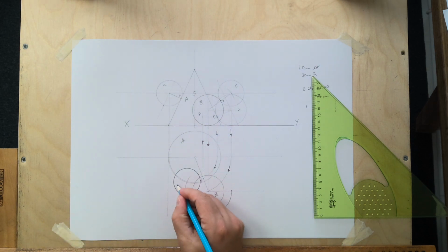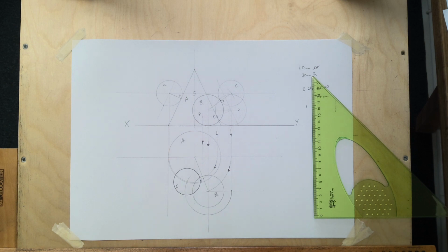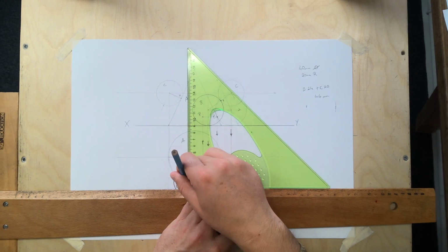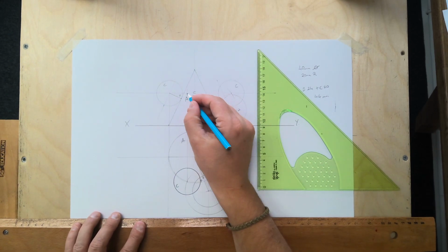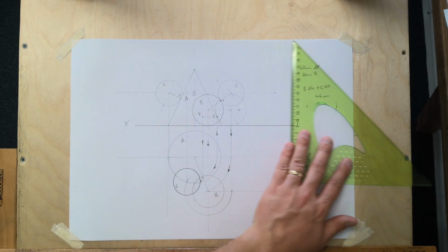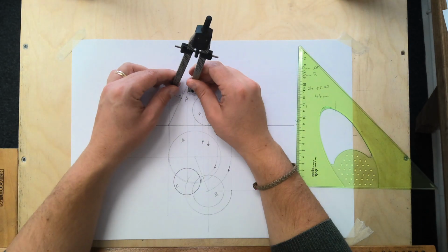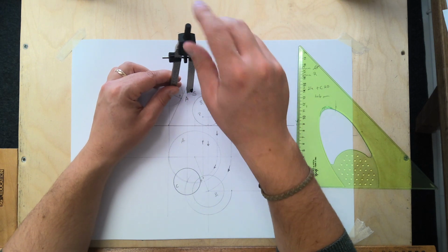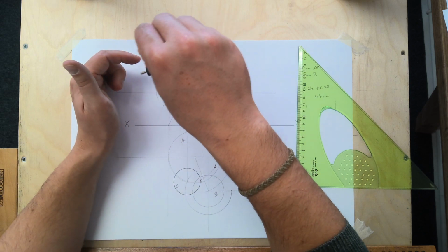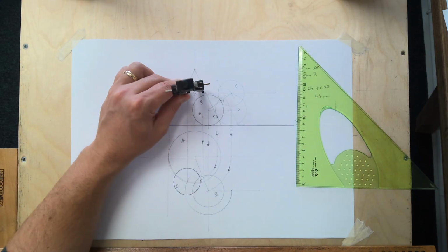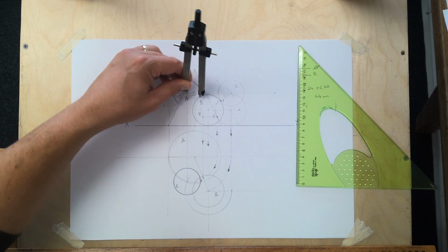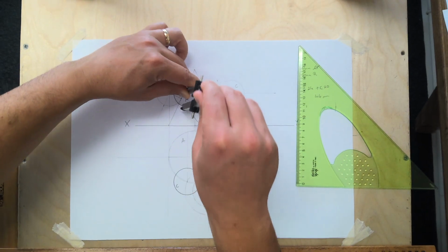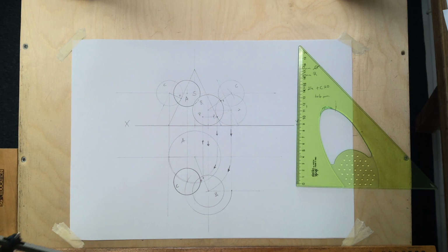Alright, so that is sphere C. We found its center point. You can now bring that up to elevation. We know it's on this 50 line, so there it is there. Now it's between cone A and B, so it's probably tucked a little bit behind B, so we'll see where it makes contact. So it's in front of A anyway. And as it comes down to here, yeah, it gets tucked in behind B ever so slightly. So we'll have a little bit of dotted line there. Alright, and that is